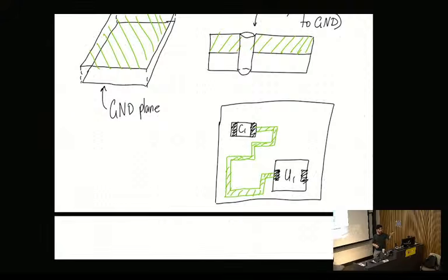Good question. So not necessarily. Where these sharp corners matter is at RF frequencies. When you're getting into the hundreds of megahertz or gigahertz range, then these sharp corners really, really matter. Because remember, at the higher frequencies, the signal is now more like a wavelength rather than just a constant signal. So the way that wavelength propagates across this PCB really matters. So generally at RF frequencies, you try and have 45-degree turns in your PCB traces.